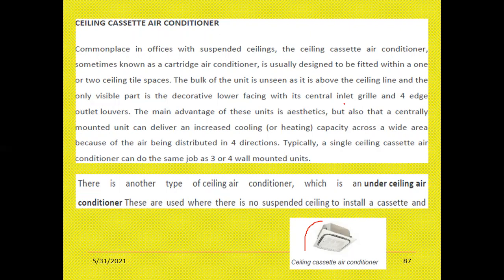Here the cooling coil is fixed in the air handling unit, which also has a large blower housed in it, right? The blower sucks the hot return air from the room through ducts and blows it over the cooling coil. The cooled air is then supplied through the various ducts into the spaces where it is to be cooled. This type of system is useful for small buildings. So direct expansion air conditioning plants are generally used for small to medium buildings and commercial places where it is cooled through the ducts.